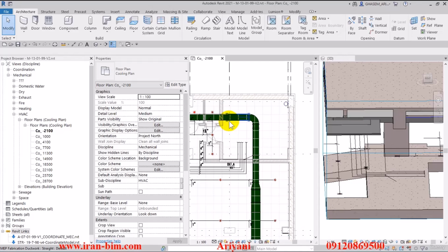So if you try to choose a family that's small or normal, and then if you run into any issues later on, it might be because the dimensions just can't add up and you run into more issues. And so in the modeling stages, when you're trying to choose the families, try to pick one that's the largest or at least a proper size, so that you resolve the issues based on this difficulty. And if later on you get to the performance stage and it's the same size, then it's great, the clashes resolve already. But if the clashes happen because the families used are even smaller, that's even better, because it's easier to get rid of the clashes and you have